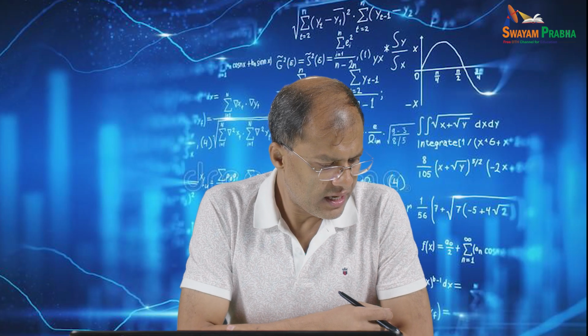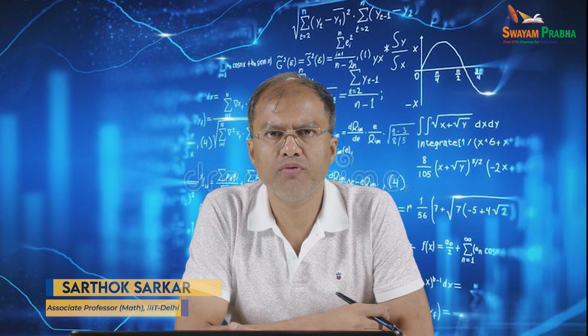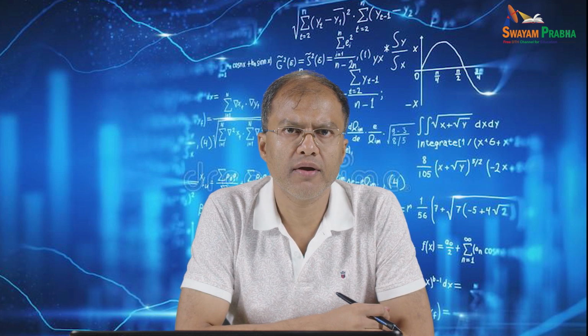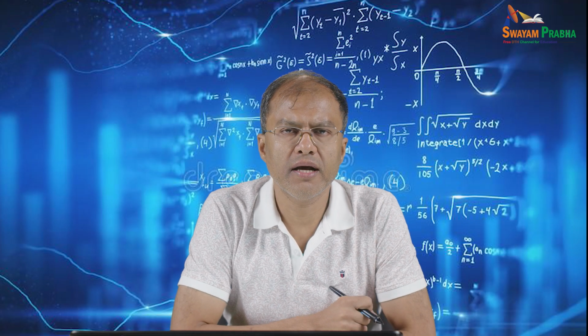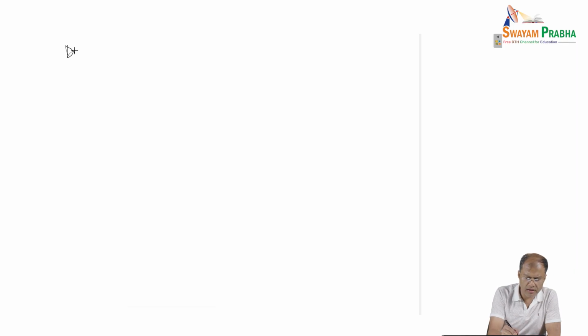Welcome back everyone, we were discussing the form of drag force, and now in this module I will try to highlight which form is necessary at what point of time, or at what values of the dimensionless group Re. It turns out that form 1 involving the function f may be used for large velocities.